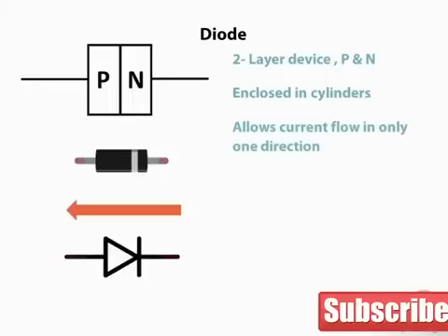This is the schematic of a diode. The leads are designated as the anode and the cathode. The anode is designated by an A, always at the triangle end, and the cathode is designated by a K. You can think of the triangles as arrows, which on schematics show the opposite direction of current flow. The reason the arrows appear the wrong way, so to speak, is that early in the history of electricity it was assumed positive charges flowed, not negative. The symbols indicated positive flow, when we now understand it to be negative flow. The symbols remained, so we just need to remember to think inversely when looking at schematic symbols.